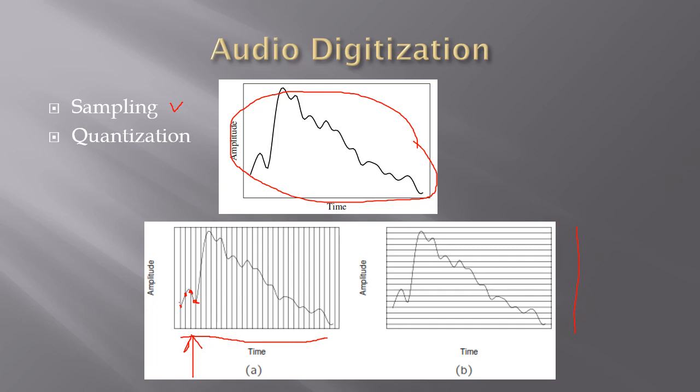So we have to do the second part, which is the quantization. Quantization is basically converting from a fraction into an integer representation. So now we have the value at this particular value only, the sampling result at this particular value only. So the number would be, if it is represented in 1 byte per data, 0, 1, 2, 3, 4, and so on up to 255.